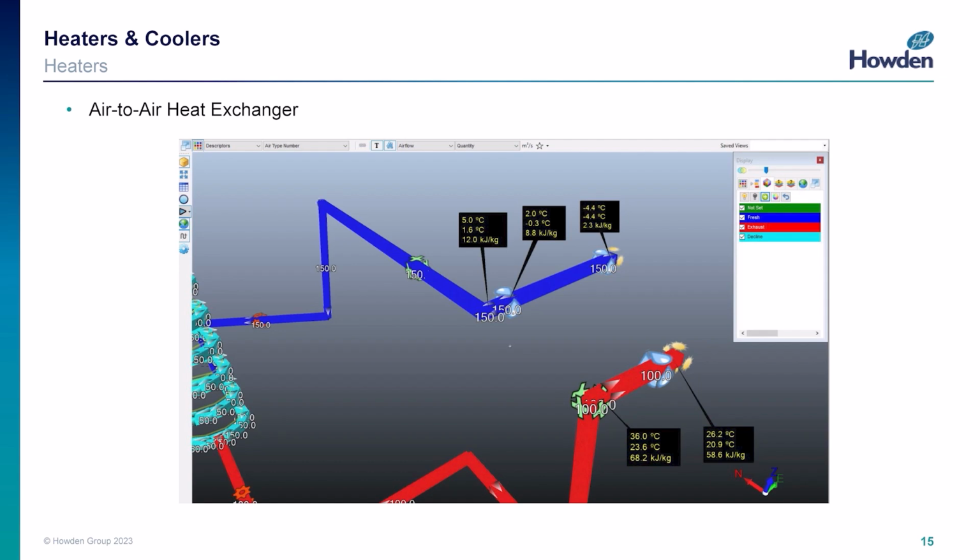Okay, so that's heat from this shaft, from this exhaust, exchanging with the air coming in to this intake. It gets it up to 2 degrees, and then I've basically set up another burner. This is like a propane backup, which is then bringing it up to 5 degrees. So you'll be able to model this in your model and then also get an idea using something like the annual thermal flywheel, you know, how this performs at different times of the year.